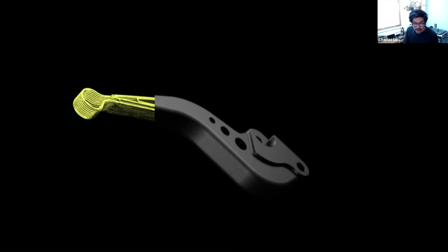I would not recommend you print on your Maker Gear M2 either, mostly because I just wouldn't want to see your machine get torn to pieces by the carbon fibers. But you know, you do it once or twice, it's probably okay. I will say that the process of printing our material on another machine is not going to be easy. We spend a lot of time tuning this stuff, right? So to get it to stick, just the bed adhesion is a question on its own. To extrude and retract properly, there's so much that goes into that.